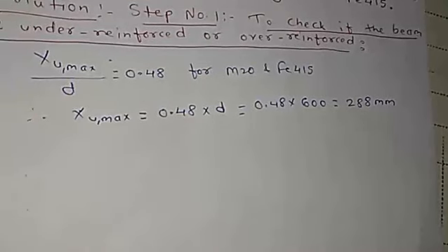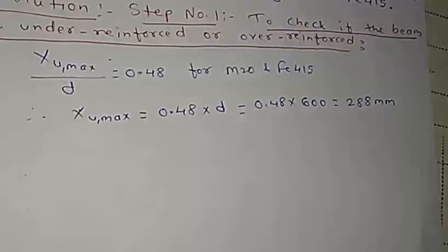And then we'll calculate the tensile strain, that is epsilon st, and that equals epsilon c into d minus xu max divided by xu max.